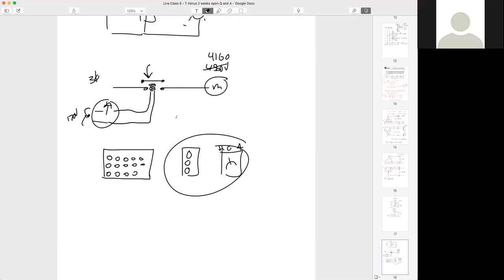So it removes us from danger, right? It takes us out of the danger. And it's much more efficient. One operator, one technician could sit in front of a relay panel and push all those buttons, start up all those motors, versus running around, right? Because you can have hundreds and hundreds of feet of 120 volt control power. It doesn't matter. Work all day.